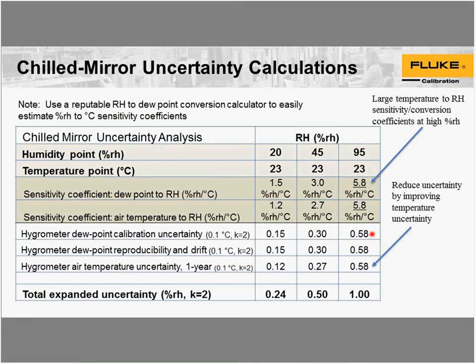We've been experimenting with a couple of different desiccants, and I suppose all of them can be regenerated in an oven. Some of them start crumbling apart if they're heated, whereas other ones are showing their integrity, not crumbling apart and maintaining shape as they are dried. Some of them have color changing chemicals added to them that the process doesn't reverse when you dry it out, so you lose the indication of how much moisture is in the desiccant.